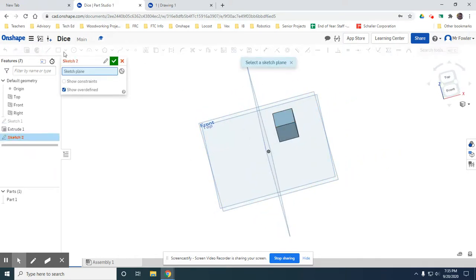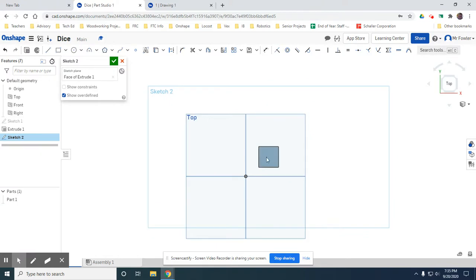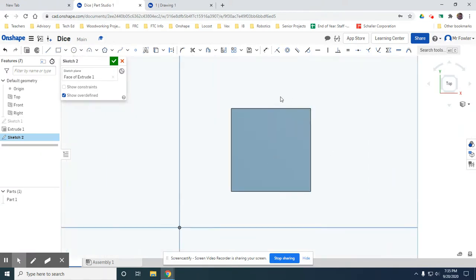I'm now going to create a new sketch on one of my surfaces. I'm going to press N on my keyboard for normal, so I switch to that normal view. We use a lot of inferences and constraints when we start drawing objects like this.